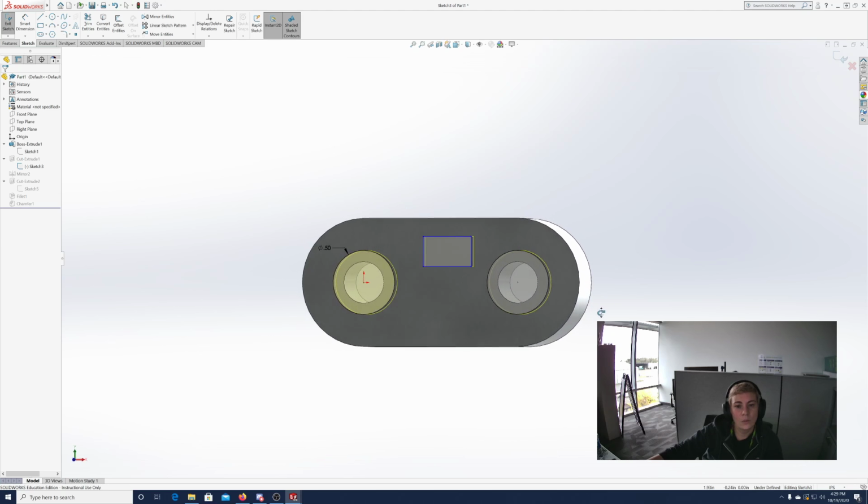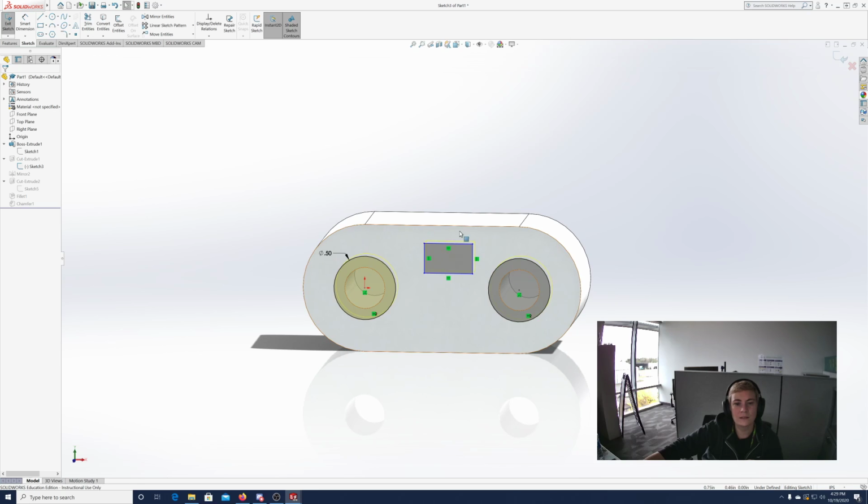And then when you're in a sketch, the easiest way to tell is that the outlines are going to be blue. Because by looking at this dash here, by looking at this underdefined down here, you know your drawing is underdefined, but you don't know what part of it is underdefined. That's where the blue lines come in handy: it'll show you exactly what it is that you need to dimension. Does that make sense?